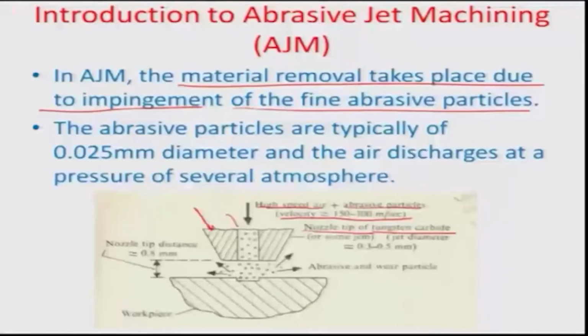Let's say we take the substrate quite close, at about 800 microns, to this abrasive jet. The jet has still not lost enough power because of the drag and other issues provided by the atmosphere, and so it produces a zone where there is crack formation, because of the continuity of these abrasive particles. If you proceed with the nozzle towards the workpiece, the zone gets expanded.